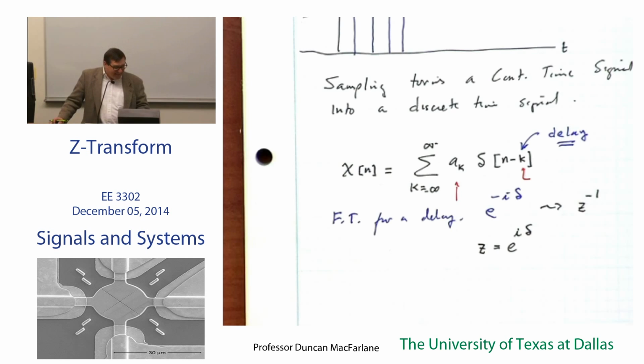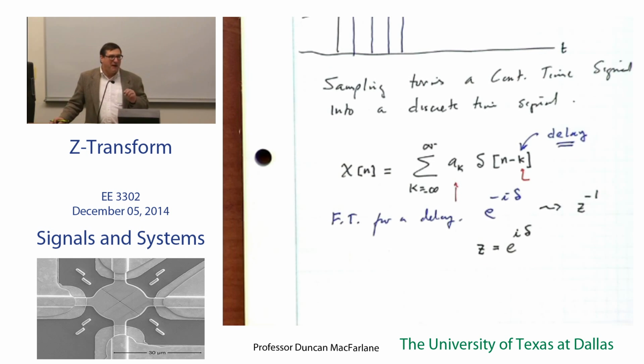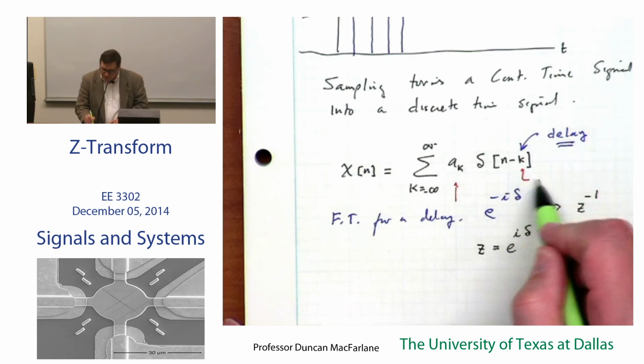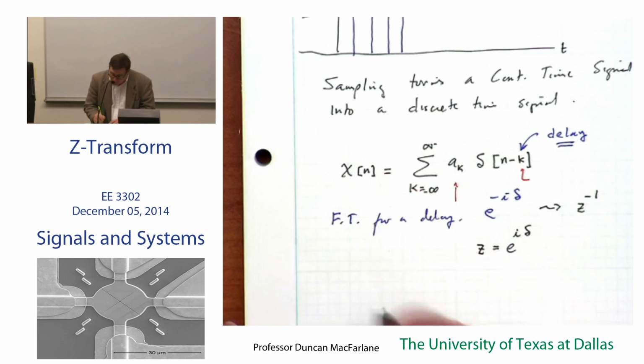And that is about as simple an explanation of what we do when we Z-transform. It may over-trivialize certain things, but it's really something you should keep in your back pocket because it completely demystifies what a Z-transform is. And for that reason, I think it's really good to let you in on that little secret. Okay? So now, if I put all this together, I have x of n, and what we want to do is transform x of n into a frequency space. If I keep track of the delays through this z term, then I'm going to have the transform x of z.